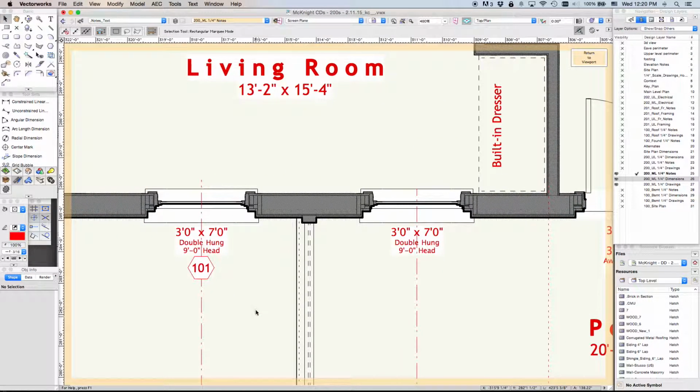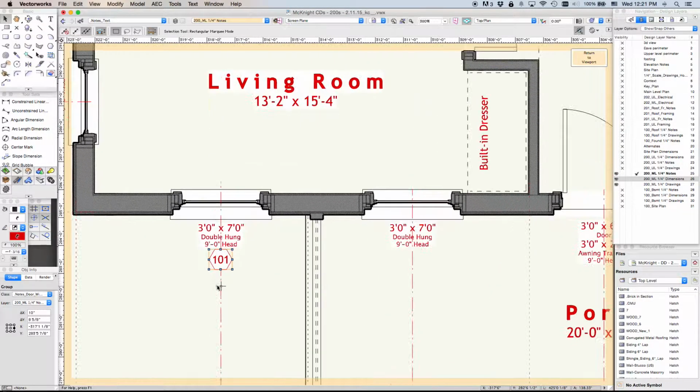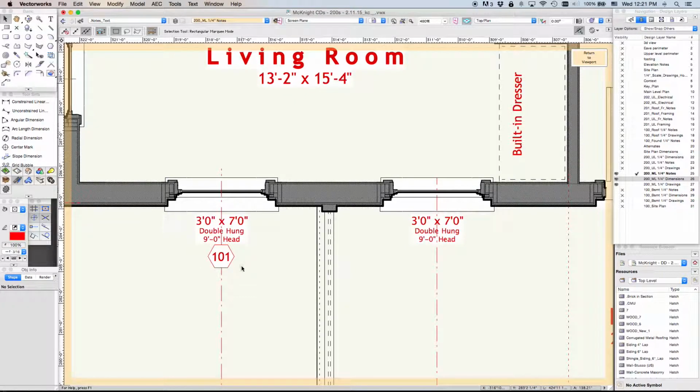So it's not really an automated tool necessarily. What I do is I start on the front elevation, left side, and go counterclockwise around the building. That way on elevations I'll show these same keys and the numbers are left to right, in numerical order. By starting here, I used to start at 100, but it's easier if you start at 101 because